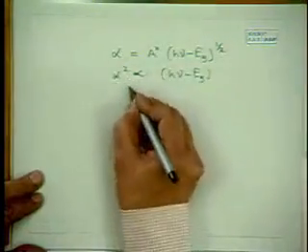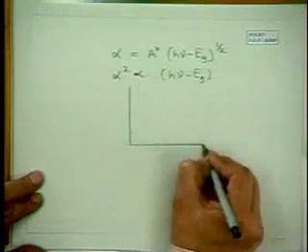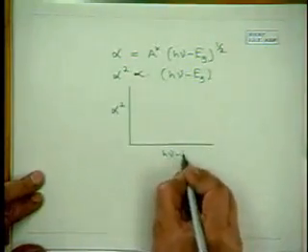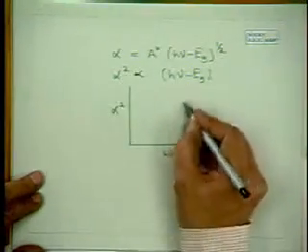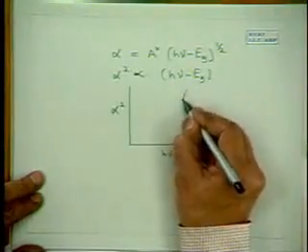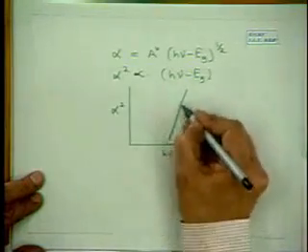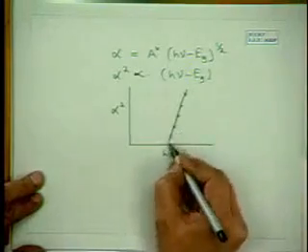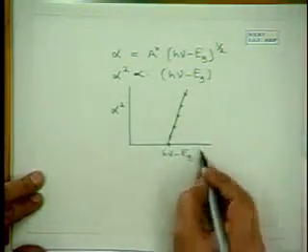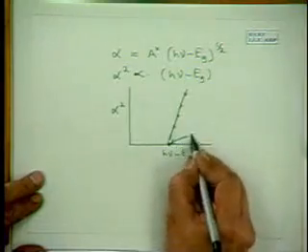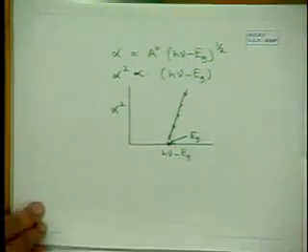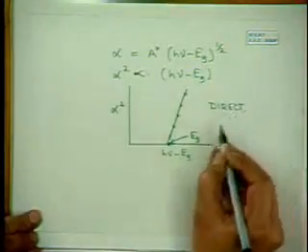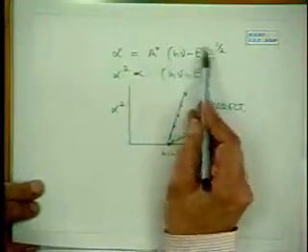So if alpha is measured experimentally, one plots alpha squared against h nu minus Eg for different semiconductors, and if one finds that extrapolation of this to the energy axis gives you the band gap of a semiconductor. So this is the test of a direct gap semiconductor, that alpha is proportional to h nu minus Eg to the power half.